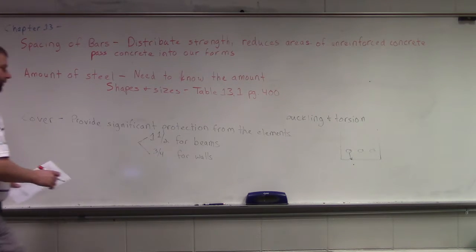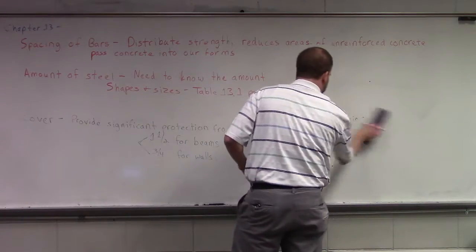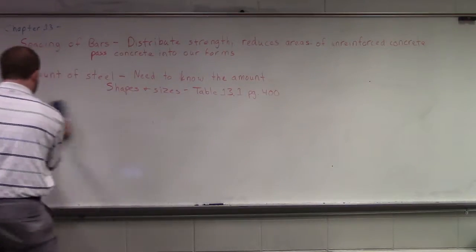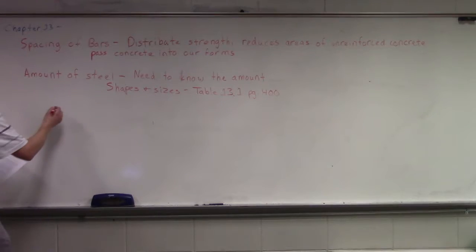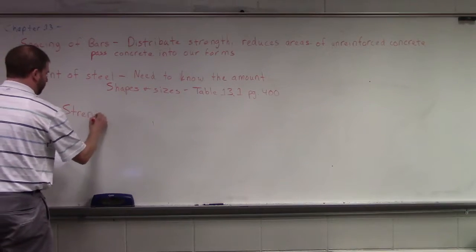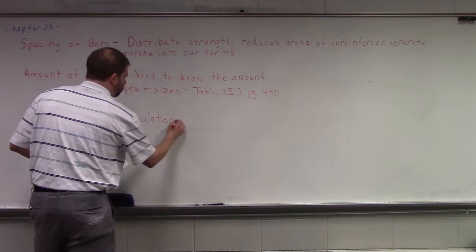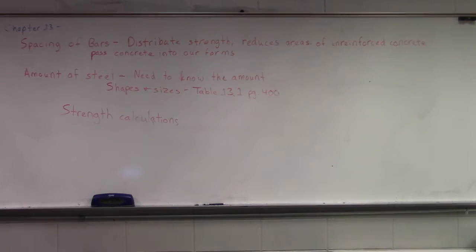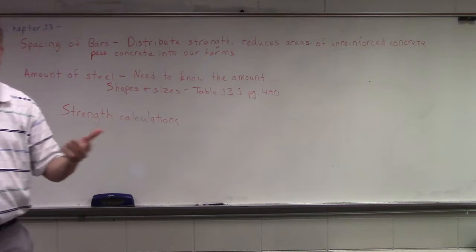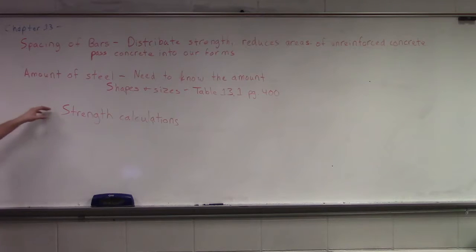So the last thing they look at before they get into the actual problems themselves is the strength calculation numbers. Up until this point, we've been drawing goofy situations. We've been making beams and trusses, putting different loads on them, and calculating axial loads, bending moments, and shear strengths. All of those numbers are used from a design consideration to determine how we size these things. That was the whole purpose.